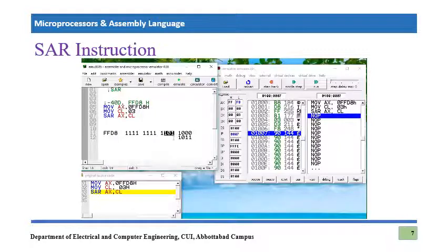101 is shifted towards right, so 1 is left only, and then this 111 from the most significant side will come up here, so that would be 111, and then only 1 is remaining, and then this 111 coming from the most significant side, so only 1 is left. So what we are going to do in arithmetic right, if you remember, these 3 bits should be filled by the most significant bit of the original number, which is what? 1. So we will be filling these locations by the most significant bit of the signed number, which is 1 always.